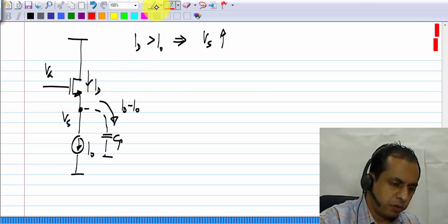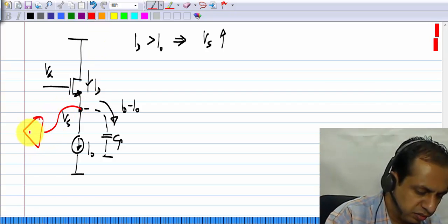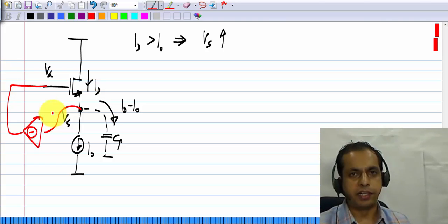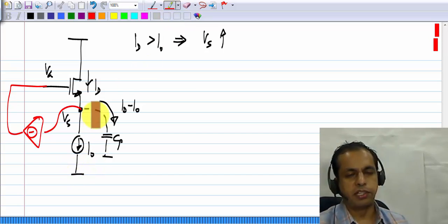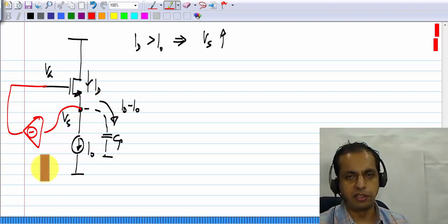Now, when you connect this additional circuitry here, there is also feedback to the gate. So, really in this circuit, although I called it sensing at the source and feeding back to the gate, we are sensing at the source, that is correct, but the feedback is both to the source and the gate, and both are in the appropriate directions.